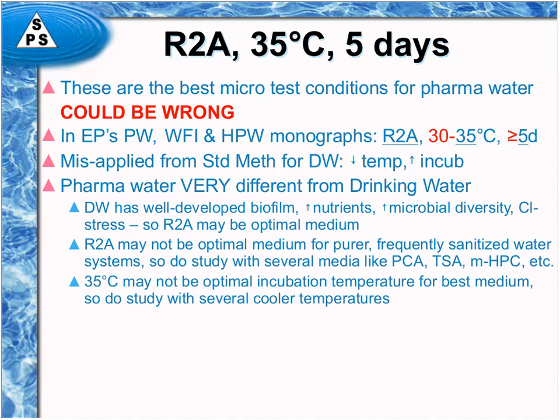Maybe cooler temperatures will work better, especially if you're in some of the northern latitudes and your water systems never get above 20 or 21 degrees. What's the chance of you having optimal recovery at 35 degrees incubation when your water system is never higher than 20 or 22 degrees?